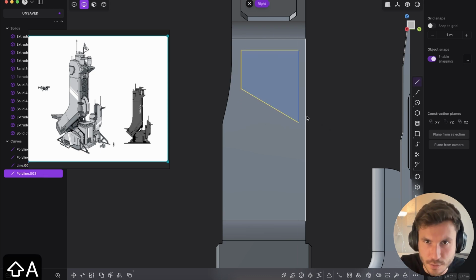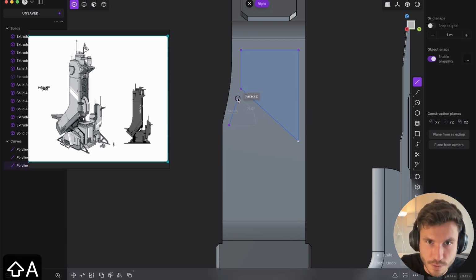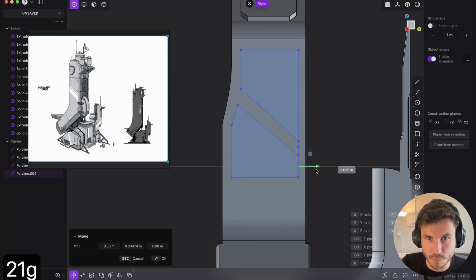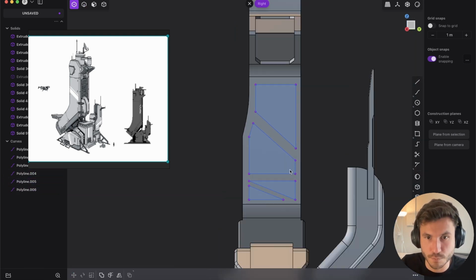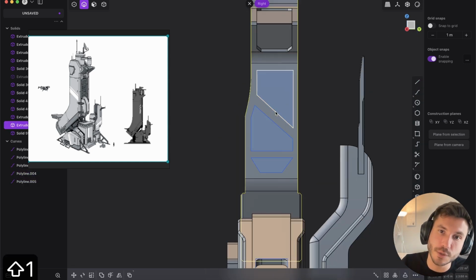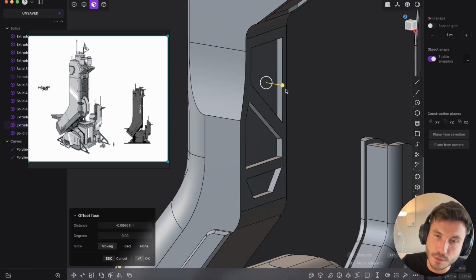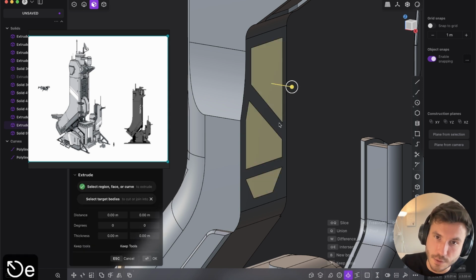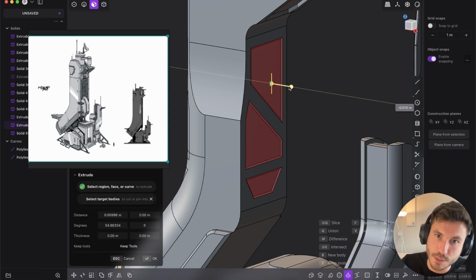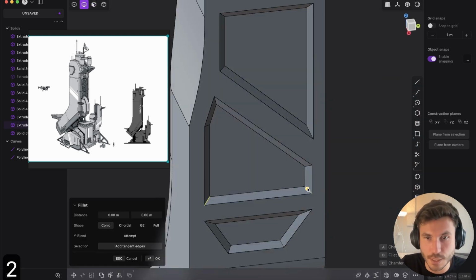And now I just want to add here some juicy kind of frame patterns or something. What you always over and over see in sci-fi. Something like that. Shift 1, again, imprint command onto our face here. And now you can just select those faces and E better and extrude them with a nice little taper. And give it some fillets.